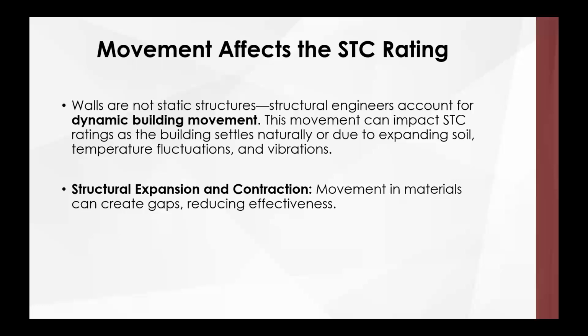Now, how does movement affect the STC ratings? Okay, let's face it, walls are not static. They're going to be moving. There's going to be some dynamic building movement, and that can impact the STC ratings. You're going to have structural expansion and contraction, and some movements that could create cracks if you're not building your wall flexible enough to be able to move without cracking.